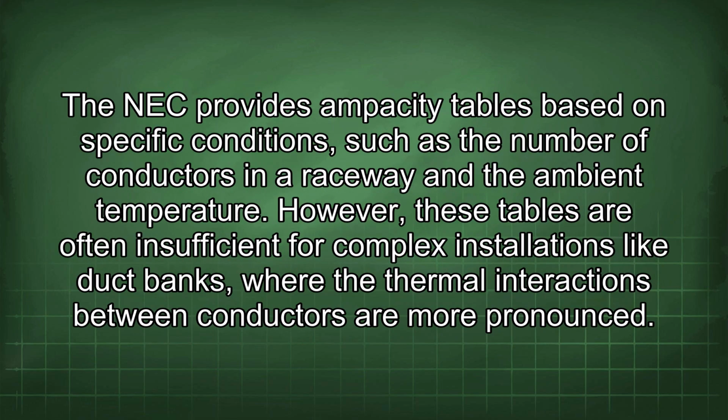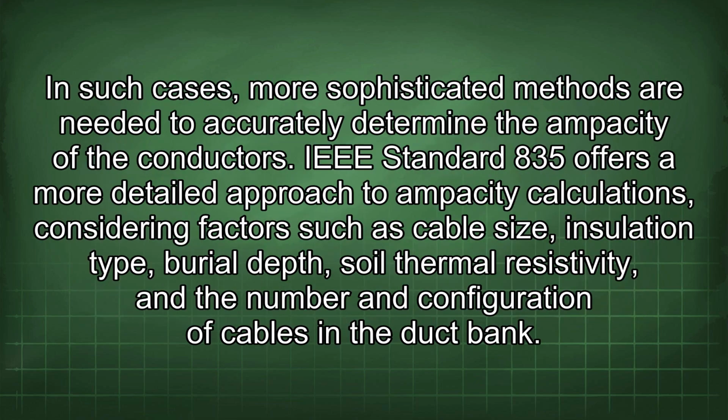The NEC provides ampacity tables based on specific conditions, such as the number of conductors in a raceway and the ambient temperature. However, these tables are often insufficient for complex installations like duct banks, where the thermal interactions between conductors are more pronounced. In such cases, more sophisticated methods are needed to accurately determine the ampacity of the conductors.